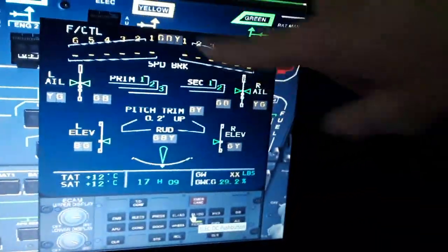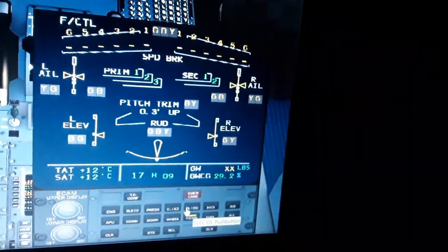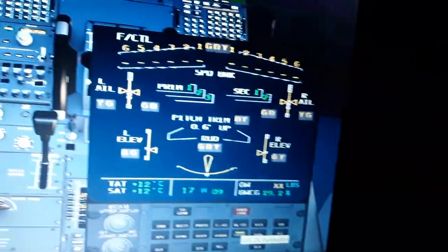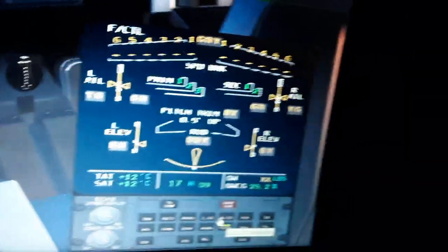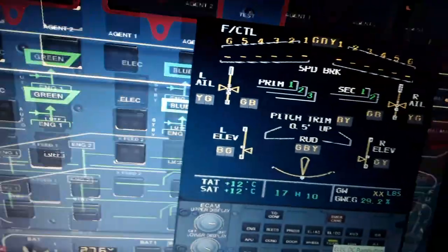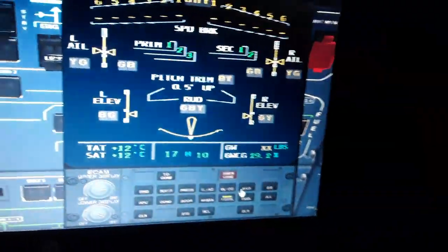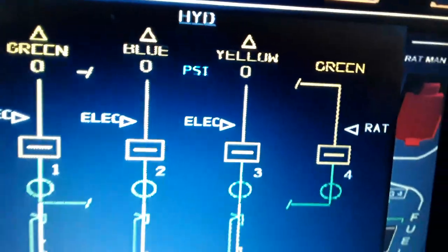You can see here now the flight controls, the configuration we have now. We do have pitch trim. We still have mechanical pitch trim through cables. The rudder is not moving, the ailerons and the spoilers are not moving. So we lose all our engines, we lose all hydraulic sources like that. With the pumps you can see now 0 psi from 3000, and everything displayed in yellow.